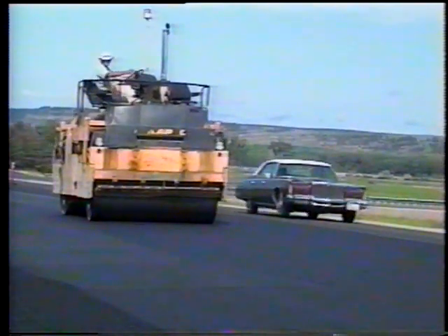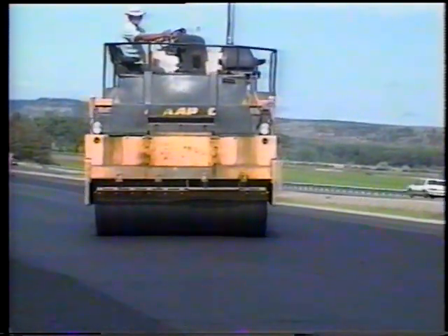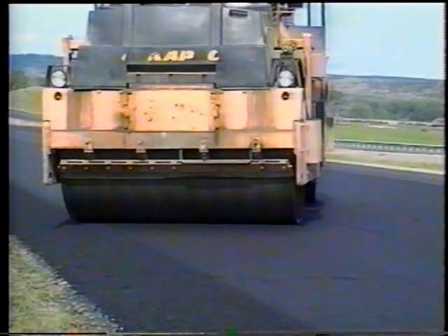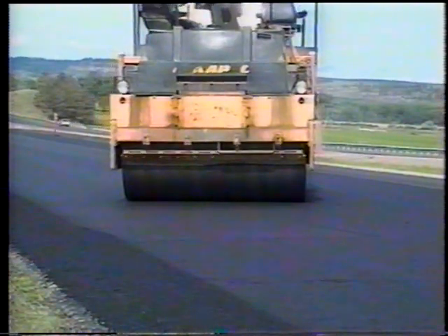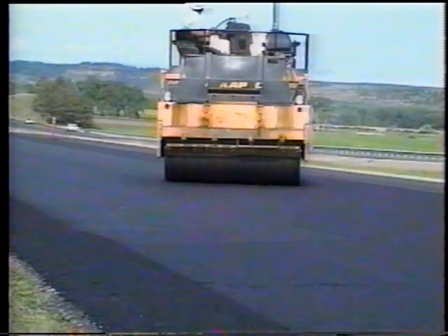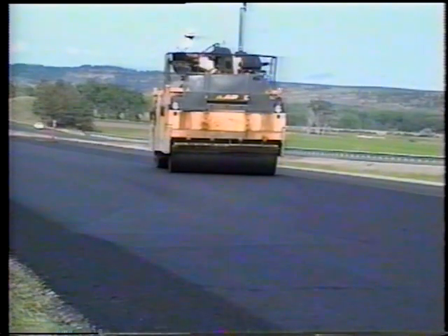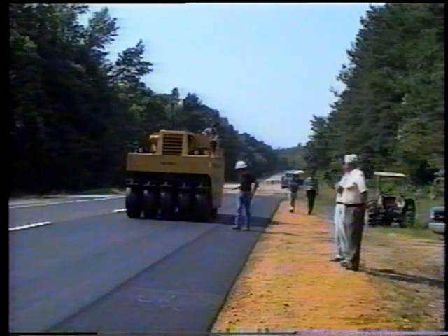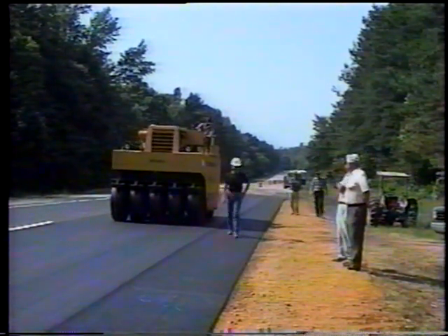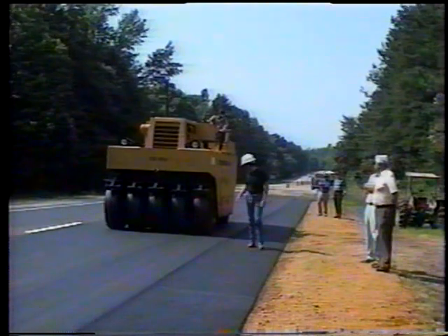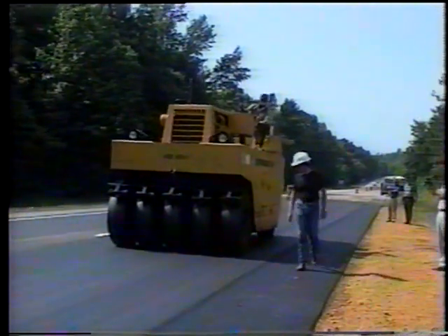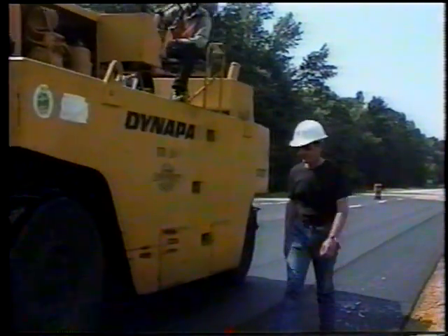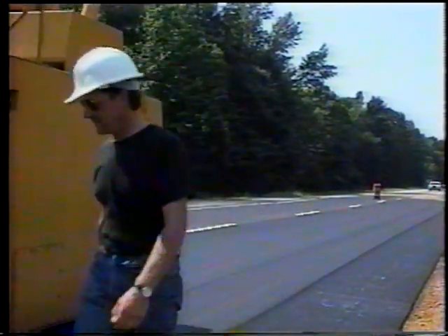Now here are some tips when you inspect the rolling. First, watch each roller as it reverses directions. It should come to a stop gradually and then reverse smoothly. And that one brief stop needed to reverse direction is the only stop permitted on the new pavement. The roller should proceed in as straight a line as possible. When turning is required, it should be done smoothly and gradually. The speed of rolling is also important. Rolling too fast can result in damage to the mat, so see that the rollers work at about walking speed.